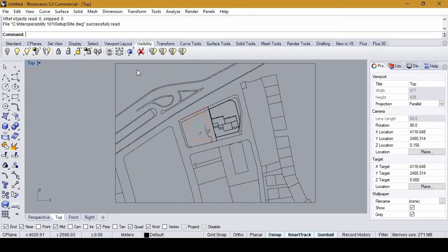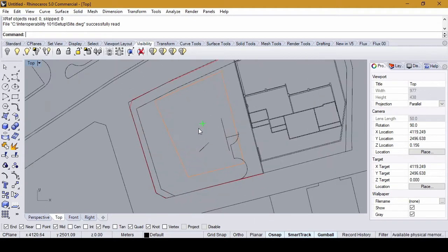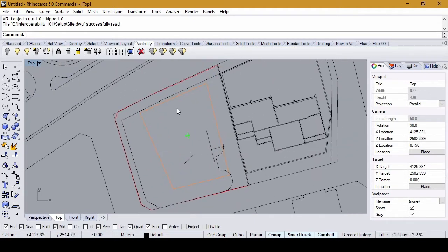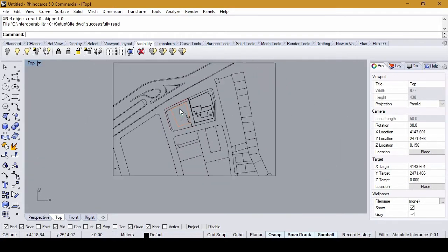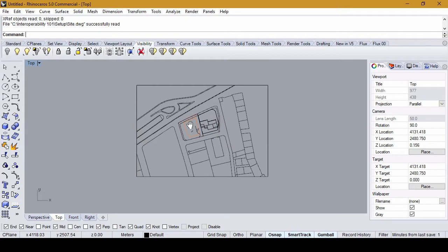Over to the top left corner is the Mediterranean Ocean outside of Beirut, Lebanon. And this is the site near the area called Mar Michael in Beirut. This map file, like so many other map files, is oriented to true north, while our building has a project north direction. So there are two things basically we're going to do in this map file before continuing to work on the design itself. We're going to move the entire site closer to the local origin of our CAD system.